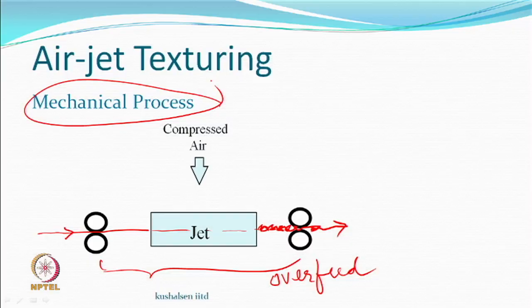But the most important thing is that it is a mechanical process. So, you do not have to worry about the chemical structure, because in the other process there has to be something called a heater, then heating, then cooling and setting. It does not matter here, it is just an entanglement process. If it is an entanglement process, viscose can be processed, acetate can be processed, polyester can be processed, nylon can be processed, it does not matter. So, the basic fundamental process does not require any chemistry, not concerned. We do everything mechanically, handle, optimize mechanically and get a nice yarn at the end of the day.